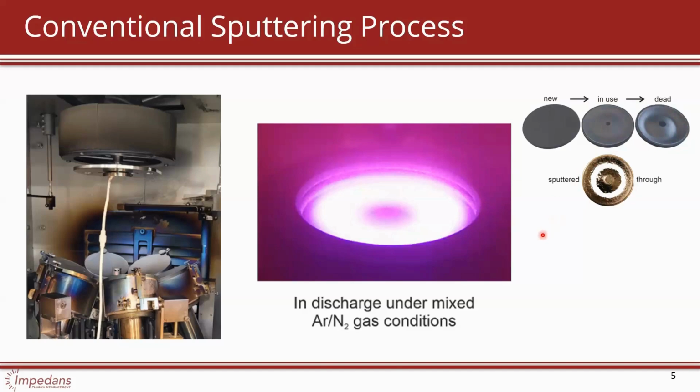Similarly, if you power a bare metal electrode, let's say an aluminium or stainless steel electrode, you're also sputtering that, believe it or not, and creating particles in your chamber. So be wary: if you have a plasma and a bias on a metal surface, once the ion energy is above 50 or 100 eV, depending on the metal, you're sputtering.